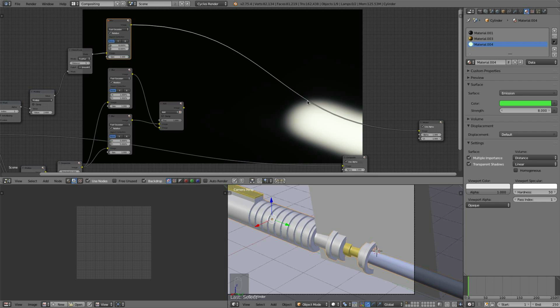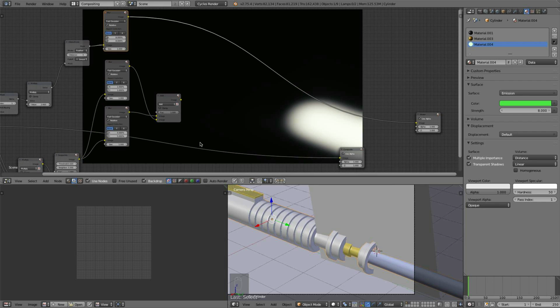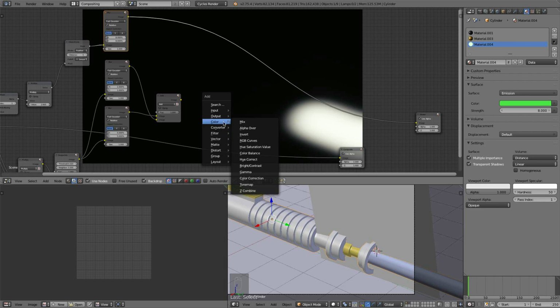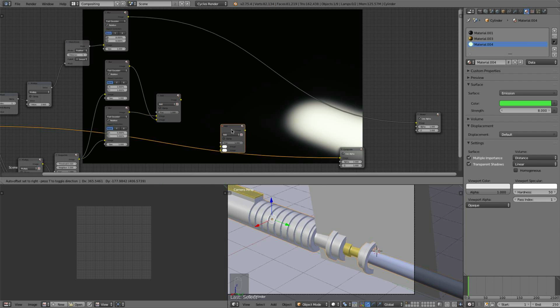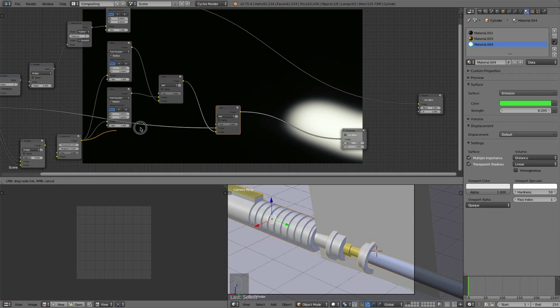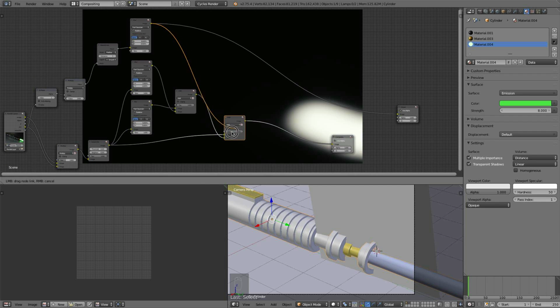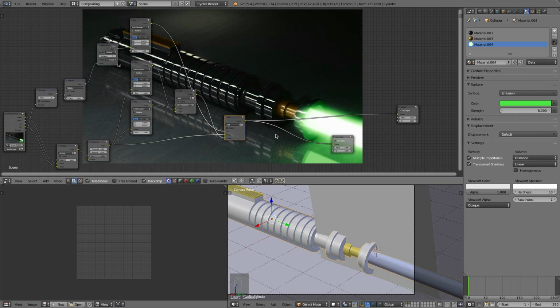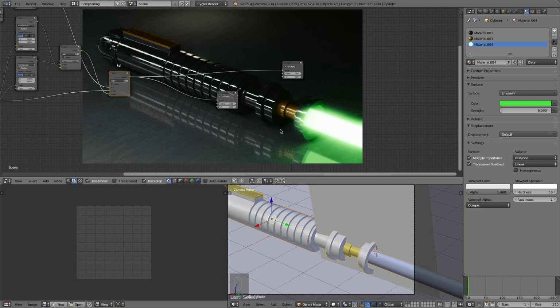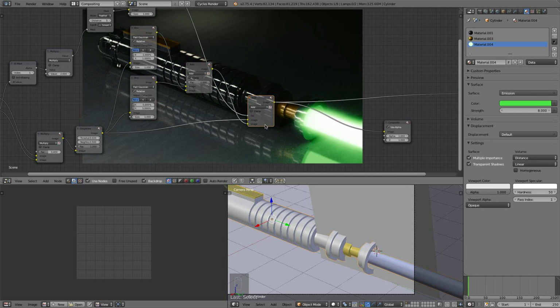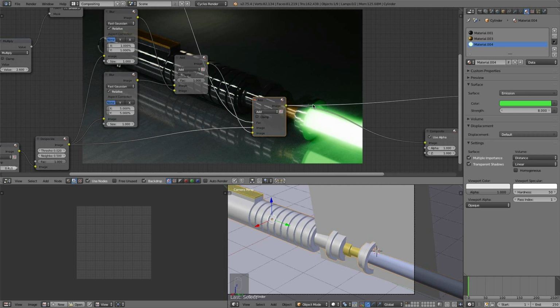And this is going to be the factor that we add these blurs back to our mesh with. So I'm going to go color. I'll just duplicate this add node right there. We're going to add these blurs to our layer here. Actually, we want this to be connected to our top one. There we go. And this will be the factor. So when I check that out now, you see we get that cool lightsaber glow appearing on top of our mesh there. Very cool.